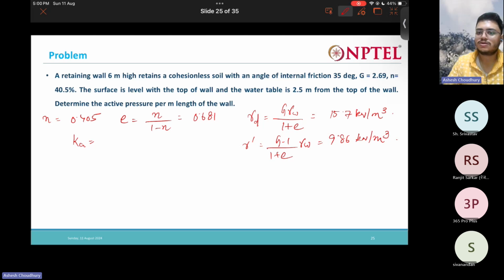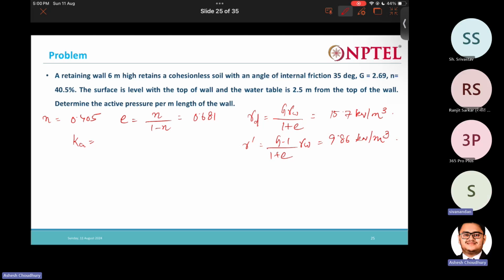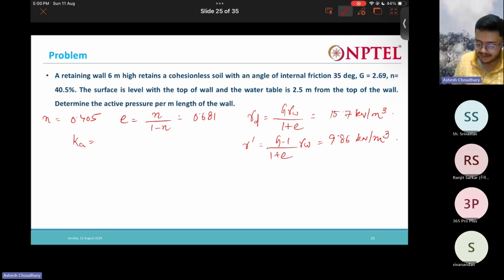You said (1 minus sin phi) by (1 plus sin phi). Yes. It is 35 degrees, right? So (1 minus sin 35) by (1 plus sin 35) will be 0.271.